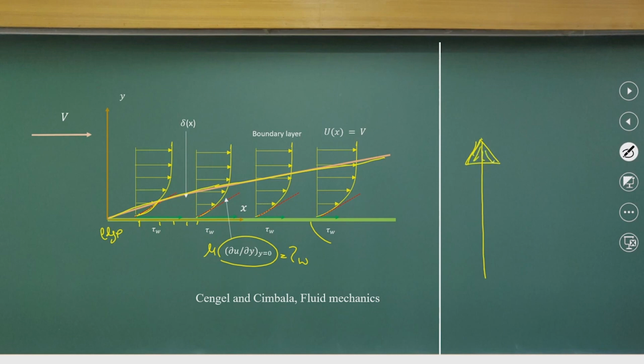So, that sharpening of arrows, you can understand how the boundary layer formation happens, and what could be the strongest materials we need at the top of the arrows. That is necessary to sustain the boundary layer formation, but the same concept is there. At the front end we will have a higher shear stress, and as you go downstream your shear stress decreases. That is the reason the materials we use at the front end of aeroplane wings or missile structures need more strength as compared to the downstream part. You can correlate it with the field conditions.